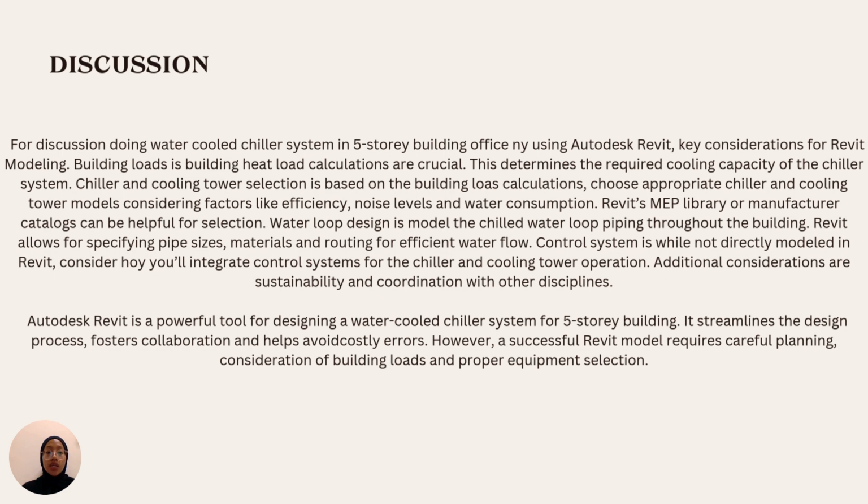This determines the required cooling capacity of the chiller system. Chiller and cooling tower selection is based on the building loads calculation. Choose appropriate chiller and cooling tower model considering factors like efficiency, noise level, and water consumption. Revit's MEP library or manufacturer catalogs can be helpful for selection.